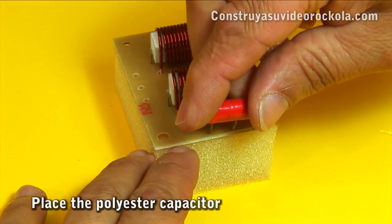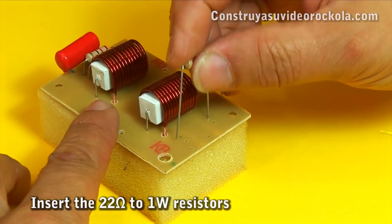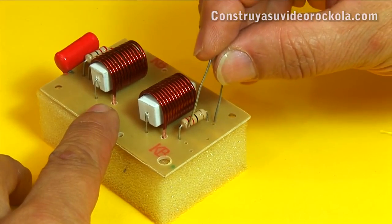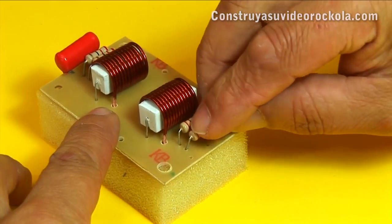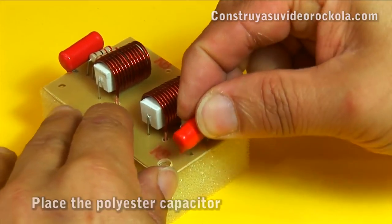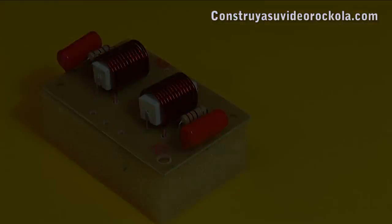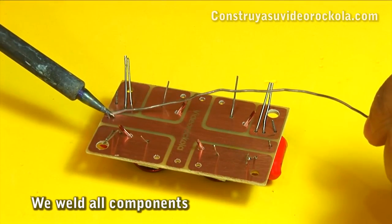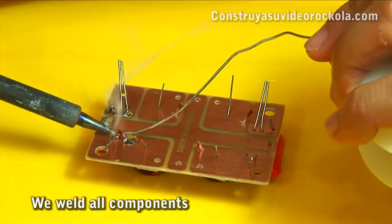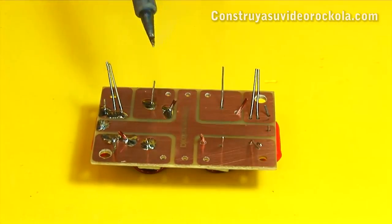And we put the 0.1 microfarad capacitor in its respective place. We place the other 2 resistors of 22 ohms, at 1 watt. And finally, we place the 0.1 microfarad capacitor. Remember to use as a guide the component mask, delivered in the PDF file. We proceed to solder all the components. Remember that the correct way to solder is joining the solder, soldering iron and parts to be soldered at the same time.